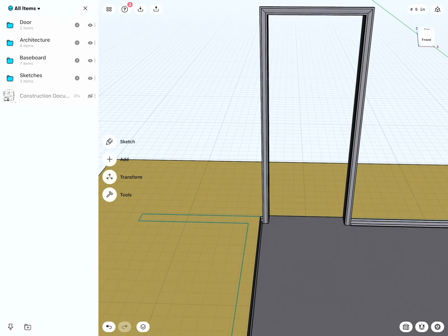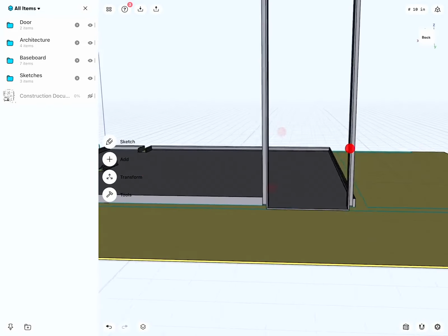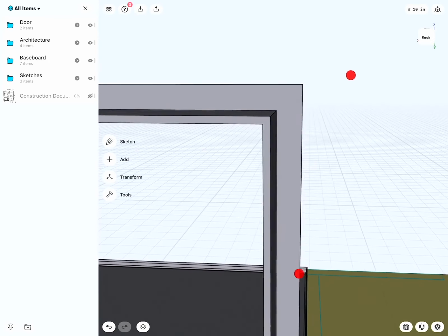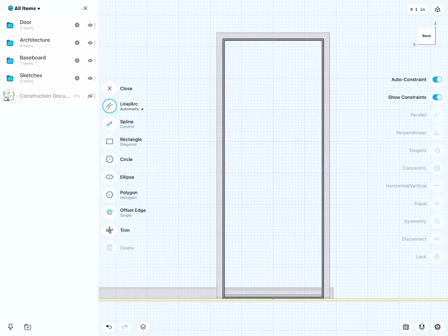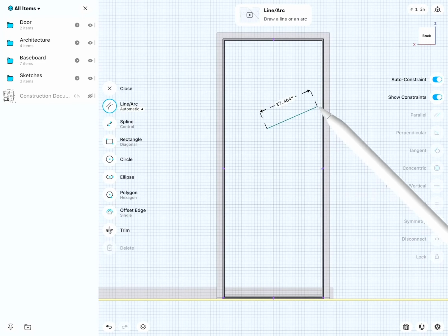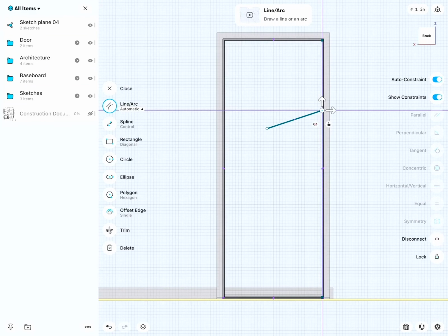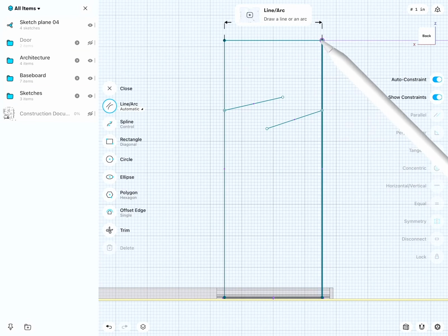Very nice. So how do we do the door? The element that goes in it. It's actually very easy to do it from this side. I will select this face with my finger double tap. And then simply draw a line. I'll make sure that this line ends actually on an inner edge. Why do I do this? Here, let's hide this. You see that? It projected the lines in. How cool is that?